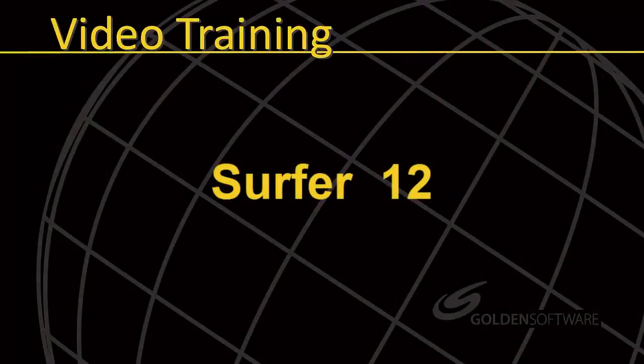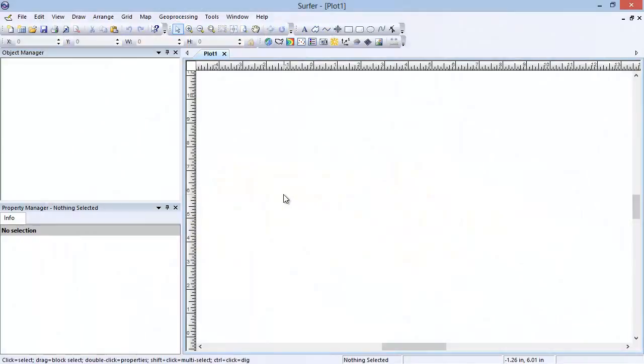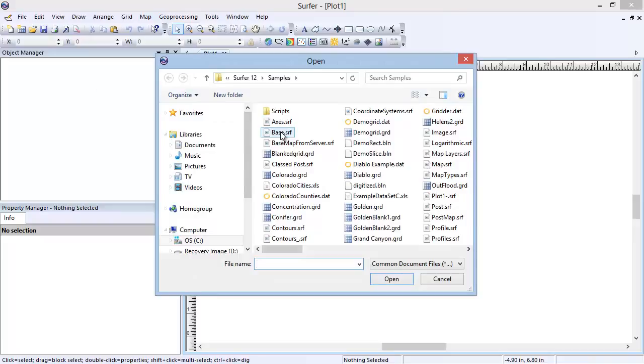This video will focus on calculating the length and area for polylines and polygons in Surfer 12. The measuring tool in Surfer can be used to easily measure objects in the plot window. To demonstrate, I'm going to open the base sample file. Click File, Open. In the Open dialog, select the base.srf file and click Open.